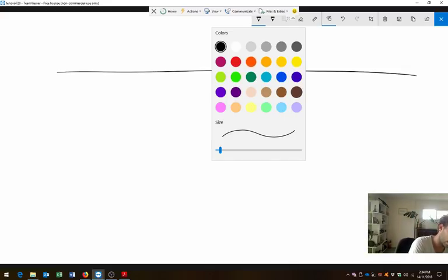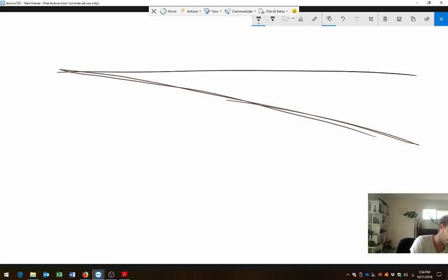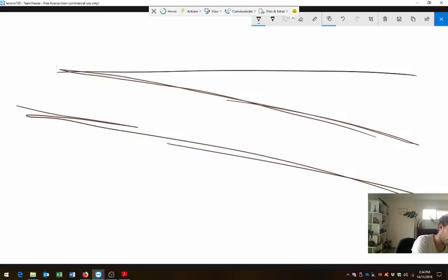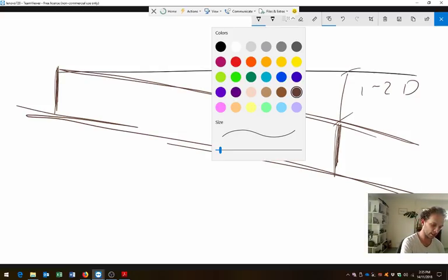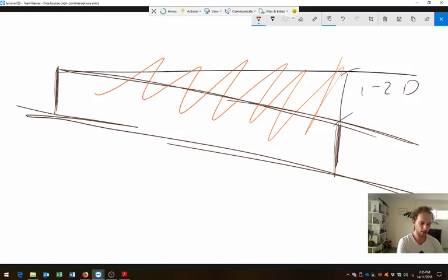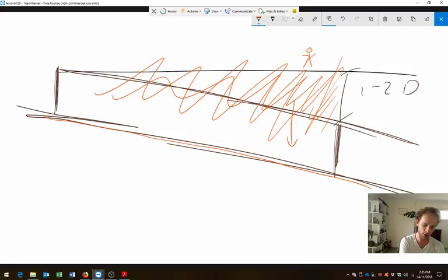So let's say we want to build a tunnel, and this is the profile for the tunnel maybe. We cannot start the tunnel boring machine here because there's nothing above it. We have to start it at approximately one to two tunnel diameters beneath the surface. For that reason, we actually have to excavate all this material here. So we could leave this, the bottom of the tunnel here, I guess, and the top open, but obviously in the city, this land's really valuable. So we want to reinstate it after building the tunnel. So cut and cover means we cut out all this material, we drop in our tunnel boring machine or the like, and then we cover over it later on to reinstate the original land use or another land use as such.